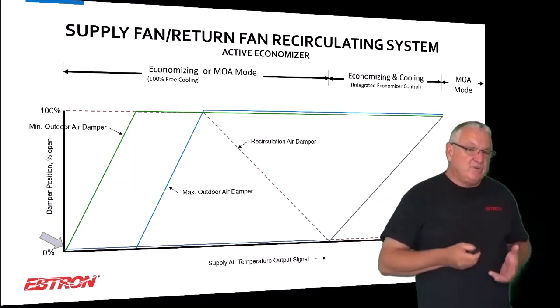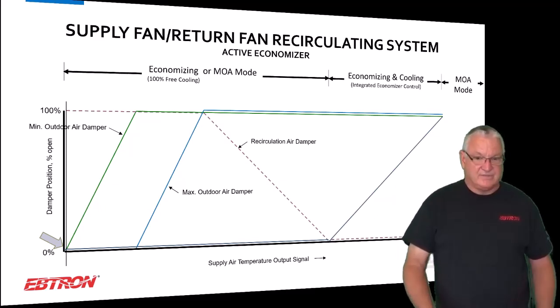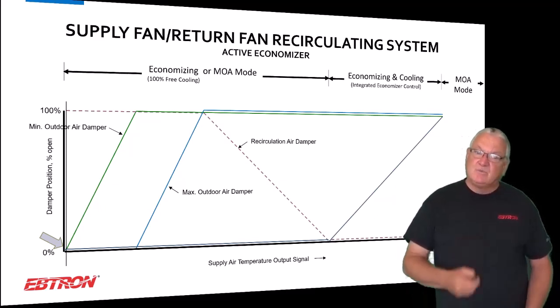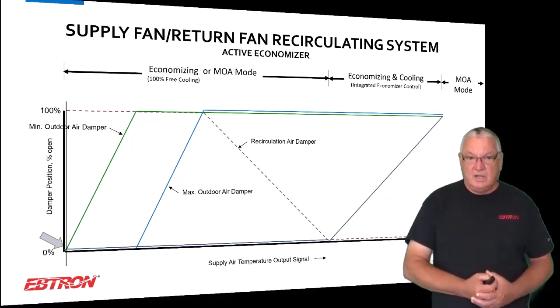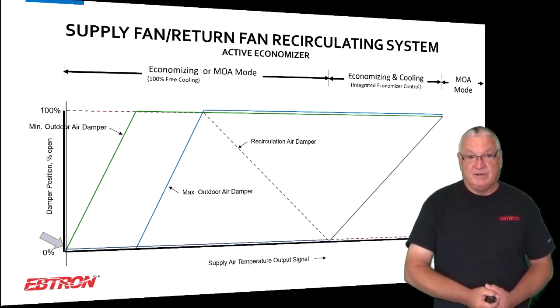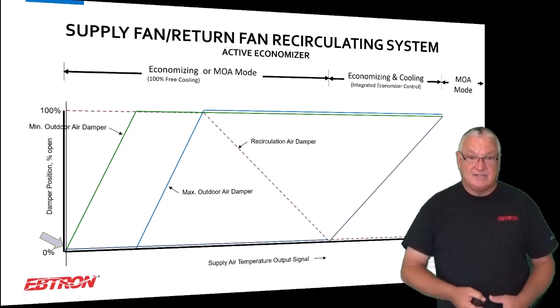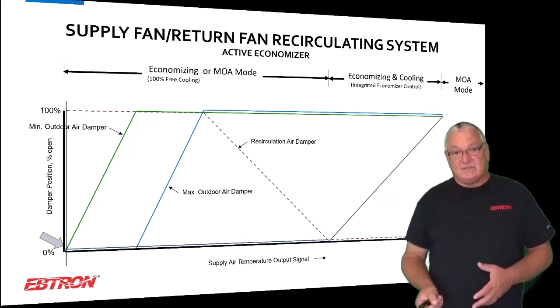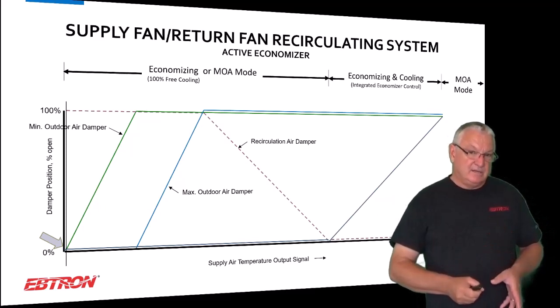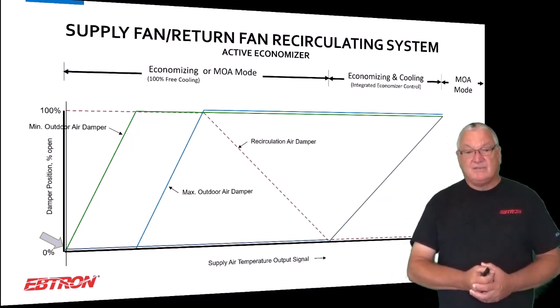Usually I say to people, and some folks get mad at me, but again, they use our stuff for min and max, and that's fine. If you use it for min and max and it works for you, I'm happy with that. But I've seen cases where min and max measurements don't always work well because the max flow can get so low that any little gusts and winds are a problem. So I say you just put a flow meter in the minimum path. If you want to put one in the maximum path and you have a different way of doing it, be my guest. Just remember that if you're in the max path and you're splitting the dampers this way, which you may not be, maybe you modulate them both together, and maybe that works out for you.